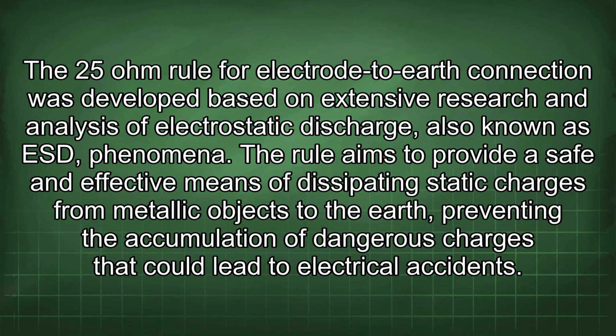The 25 ohm rule for electrode-to-earth connection was developed based on extensive research and analysis of electrostatic discharge, also known as ESD phenomena. The rule aims to provide a safe and effective means of dissipating static charges from metallic objects to the earth, preventing the accumulation of dangerous charges that could lead to electrical accidents.